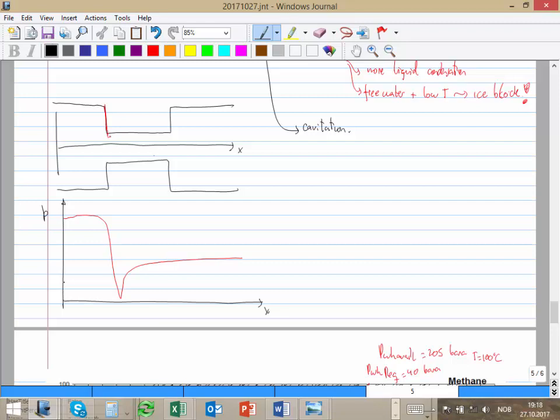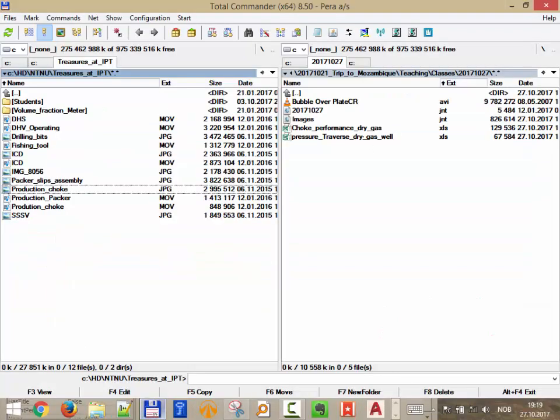So what might happen is that you're working with liquid, and here you have the vaporization pressure of that liquid. When you go down, actually here you're vaporizing liquid in the throat, exactly here, and then here it becomes gas and here it becomes liquid again. And that process causes this cavitation that I told you about.